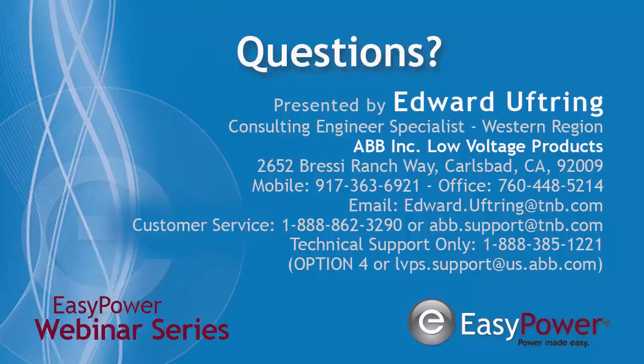What is the optimum number and rating of spare breakers to be recommended for a new installation? You know, that really depends. The ratings depend on what your application is calling for. The spare breakers, we usually do not see the need for a lot of spare breakers. We do quality checks at the factory before they go out, so each individual breaker is tested under load, and we know that it is okay. Some of the standard practice is usually you carry about 10 extra breakers because if you're blowing through more than 2 or 3 breakers on a job, typically there's something really wrong with that job. Again, the breaker should open before it gets damaged.